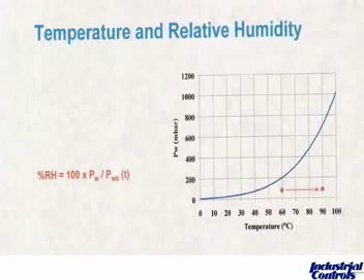And the next slide is just going in the opposite direction. We have a temperature of 60 degrees Celsius with a known moisture content. Without adding or taking away any moisture, if we were to increase the temperature up to 90 C, you can see we are that much farther away from the saturation curve. Therefore, you're going to have a much smaller relative humidity value.